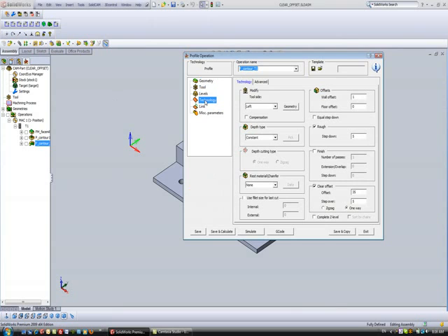And in my technology area, we've used the option here of clear offset, where our offset is 35 millimeters out and stepping over every 5 millimeters. Soon we'll pay attention to how we can use complete Z-level and sort by chains.